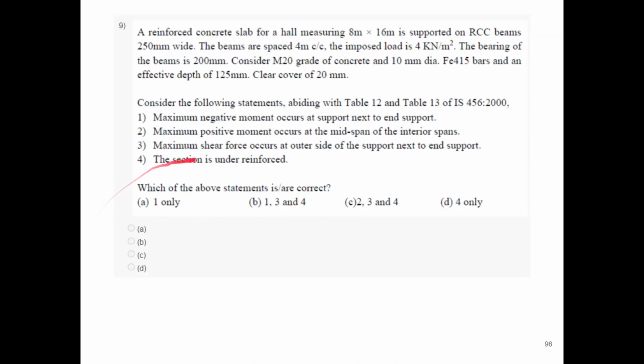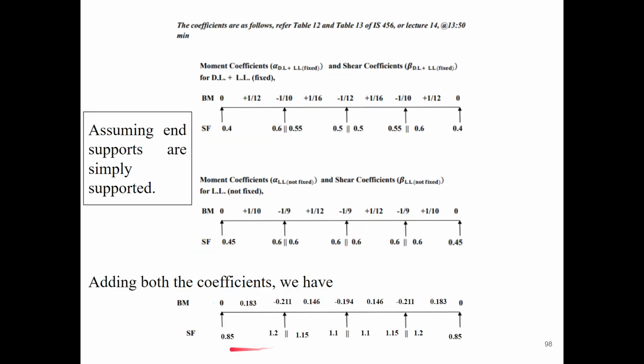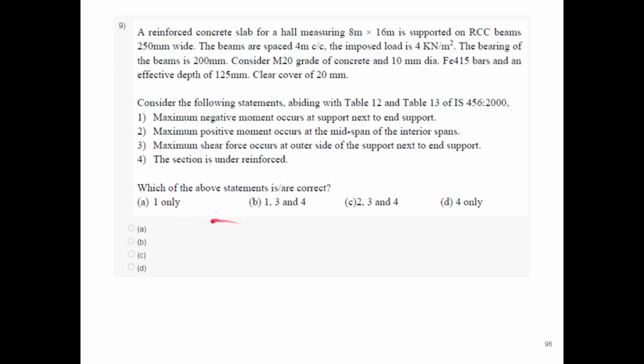From this we can say maximum negative moment occurs at support next to end support. So statement one is correct. Now, maximum positive moment occurs at the midspan of the interior span.